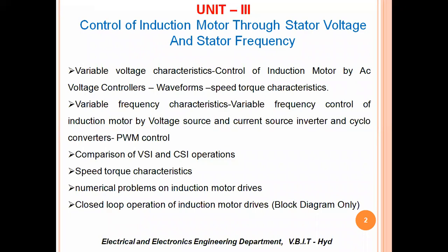That can be carried out with the help of AC voltage controllers. We will see the circuit diagram of control of induction motor with AC voltage controllers and the respective waveforms along with the speed torque characteristics. In the speed torque characteristics, we also find the voltage term, because we need to see how the torque and speed relation changes with respect to the stator voltage.